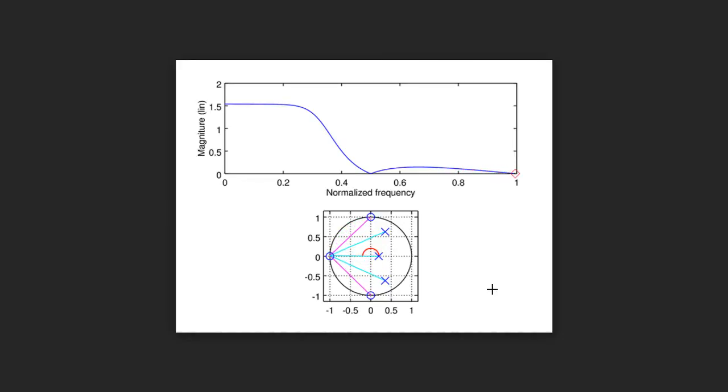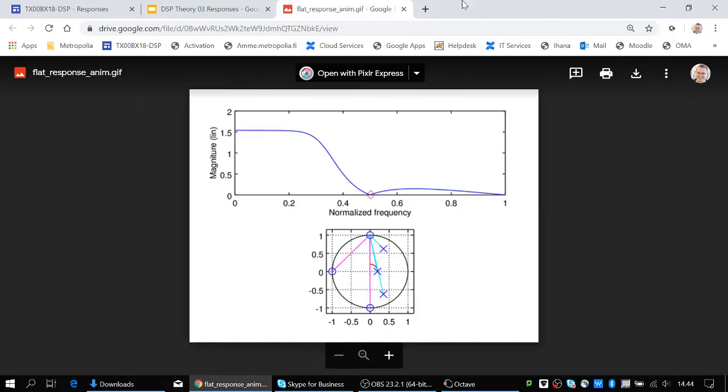So second order Butterworth low pass filter has poles there. Right. Third order, you just have those here, here, and here. Quite similarly, they are not anymore actually on the circle, but they are in a kind of elliptic formation there. Good.